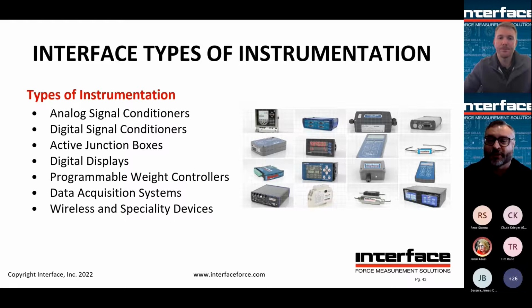Upper left, you see a weigh controller, quite fancy, with lots of weighing functions. You also have basic amplifiers and signal conditioners. A lot of times there's a PLC that just needs a 4 to 20 milliamp signal related to load, so we can do that. Sometimes just a basic display that shows pounds if somebody wants a visual representation. But some of those displays can have analog or digital signals back to a PLC or controller. Some DIN rail mount amps can have little displays on them and take the 4 channels, or however many channels in, and sum them together and give you a total plus the individual weight. So lots of different options. Moving on to the next slide.